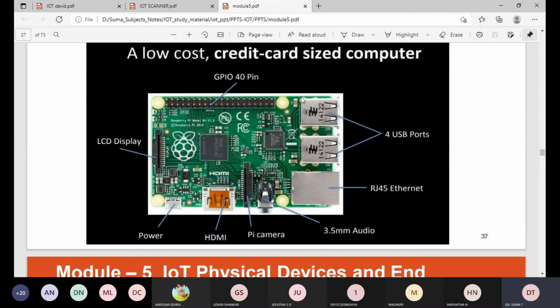The Raspberry Pi connector S2 is a display serial interface for connecting a liquid crystal display panel using a 15-pin ribbon cable. The Mobile Industry Processor Interface inside the Broadcom BCM2835 IC is going to feed the graphics data directly to the display panel through this connector. This article looks at the connector pinout and some of the display panels compatible with the port.